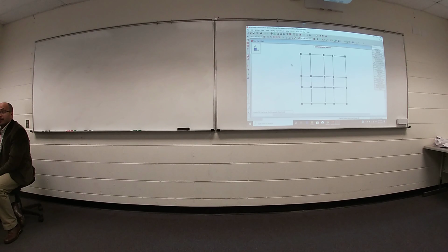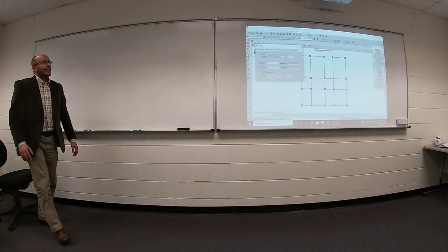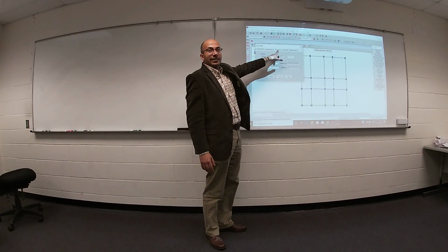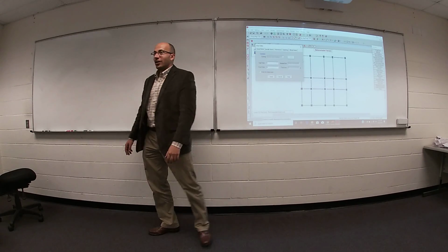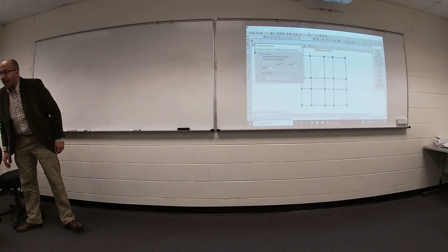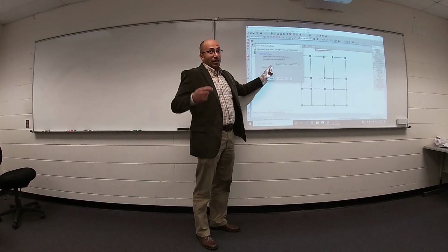Can you repeat that step again, please? For slab, yes. Insert, slabs. Where is the thickness? How can I define my thickness? So you need to hit this one. That's right? Okay. Go for thickness and define your thickness. That's right?